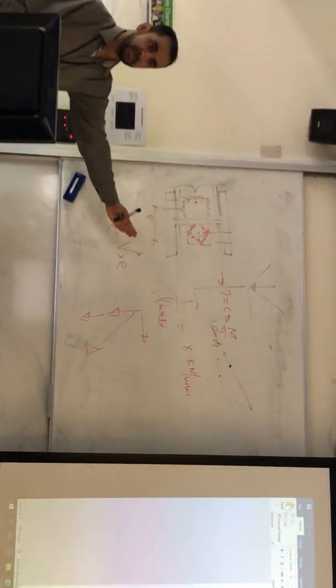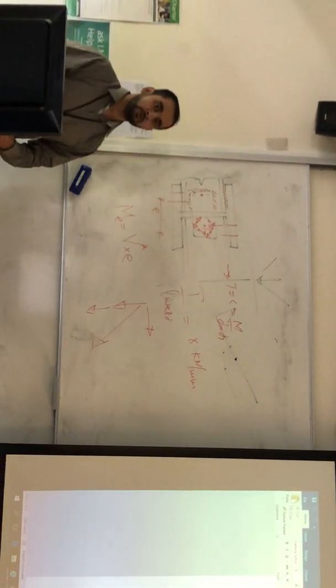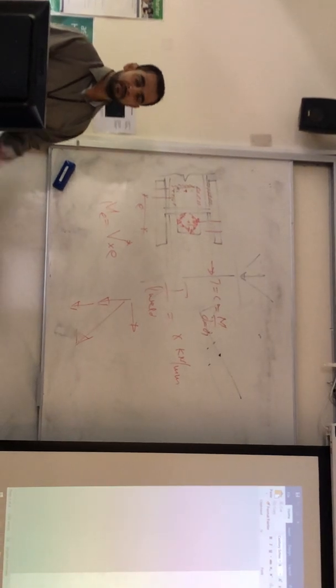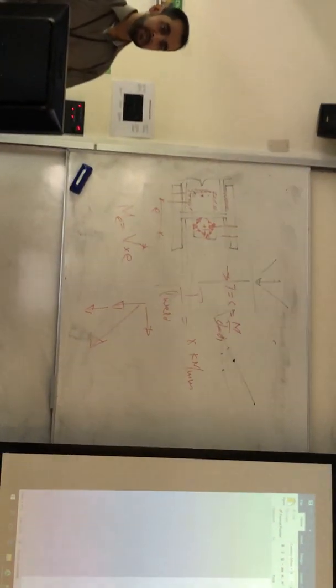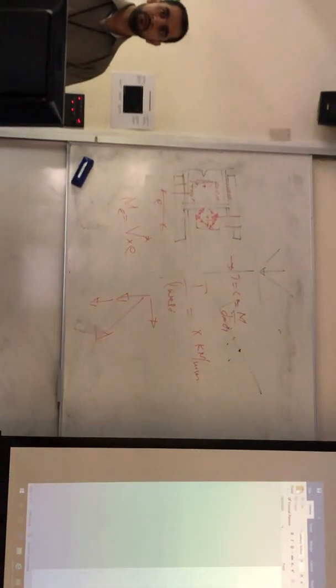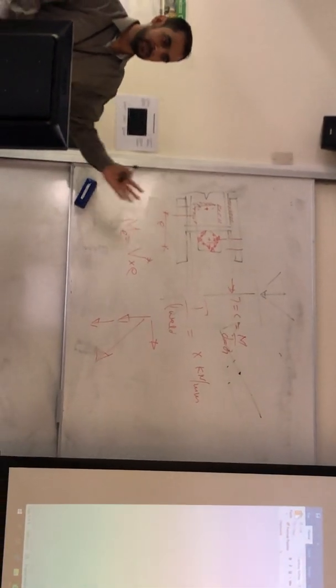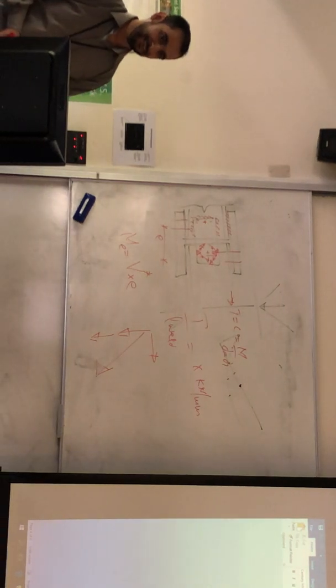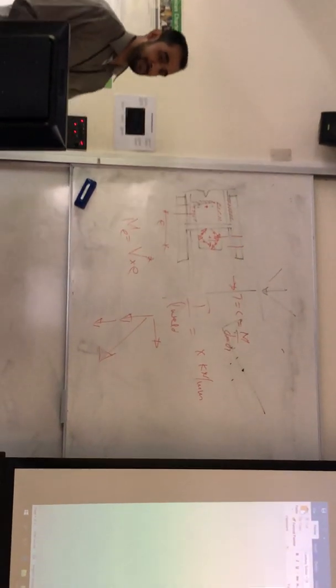That's it, that's your design action, that's your shear force, go and check the bolt. There's nothing hard in it. And then on the other side you got the welds, do exactly the same for the weld. There was the web splice, and that's all you have to do, it's simple as that.